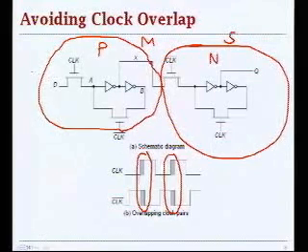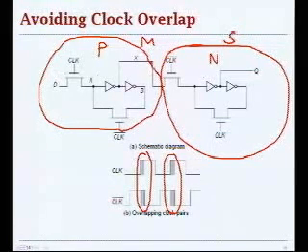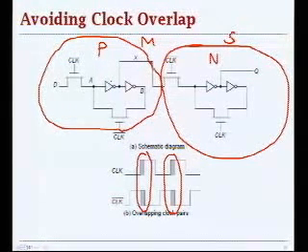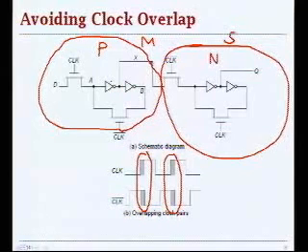So you are coupling your input all the way to the output when you think that your latch is in the hold mode. And that's the problem. You have to really make sure that situation doesn't happen, because what you want is, when you get an edge of your signal, that the previous latch is blocked, that it decouples the incoming data, and that you can only copy whatever was stored at node X.